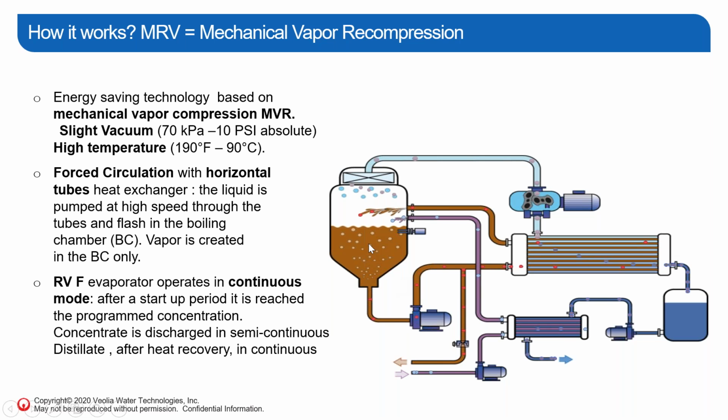But the important point here is that you're always going to be discharging a portion of this condensate. It starts on semi-continuous, but once the system is running, it can be a continuous discharge of the concentrate, so it's easy to operate. The discharge is more or less controlled on time or density. So basically, once you reach certain densities, then the concentrate will be ejected. So they're really a self-contained system, and as I mentioned, it's all standard units with the remote support. So we have a lot of support to the operators as well.